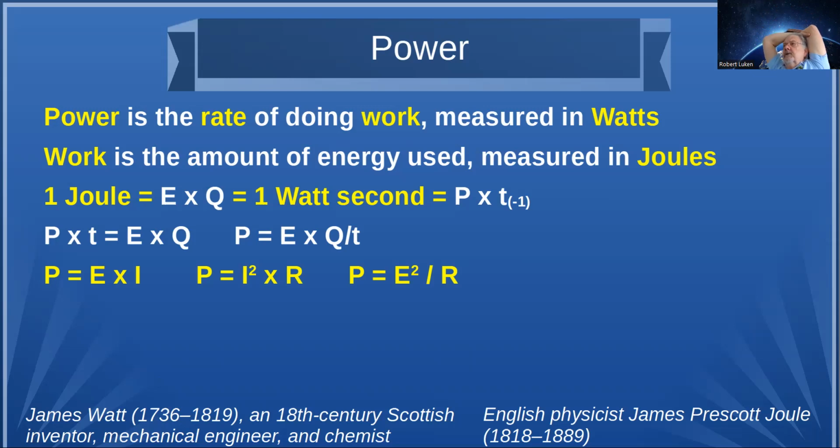The connectors typically aren't a problem. If you install, and you should, lightning arresters in the feed line, those will have a power rating, because most of them work with a little gas discharge tube that arcs over at a certain voltage.